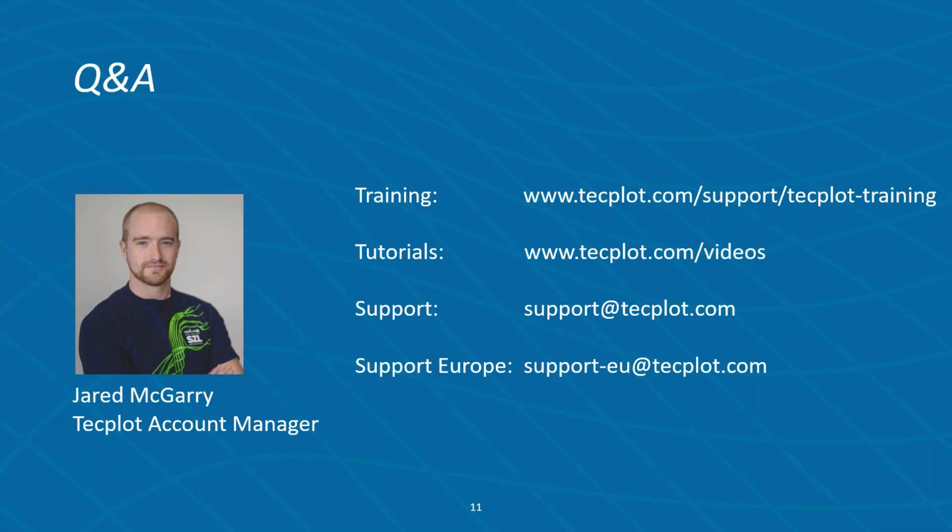Can you import shape files? So the answer is yes, but we don't have direct support for it. We do have a Python script available on TecPlot's GitHub page, which can convert shape files to TecPlot binary PLT format, and then you can import it there. In the question panel, I included a couple of links to a video that Jared did, and the Python script.